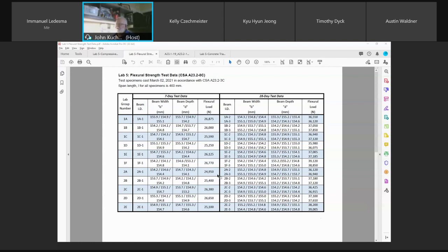And you can see just by looking at these flexure strengths as compared to compression, they're quite a bit lower. Typically, flexure strength is about 1/10 that of compression when you're talking megapascals. When you're talking imperial or PSI, flexure would be anywhere between 7 to 8 times the square root of compression. But if you've got a cylinder that tests roughly at 44 MPa, your flex is going to be somewhere around 4, 4.2, 4.3, approximately 1/10.